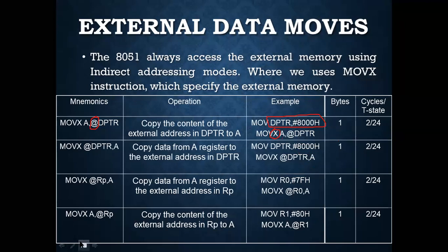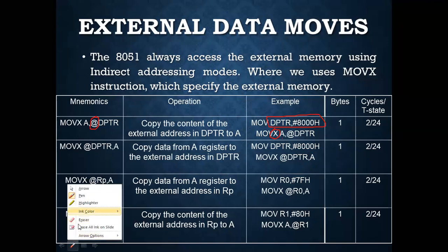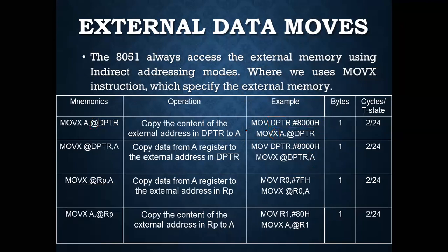Now you may ask, sir, there is written 1 byte. Please don't focus on the initialization instruction; only focus on MOV DPTR and MOVX A, @DPTR. No 8-bit data is there, only mnemonics along with the registers, so it is a single byte instruction. Similarly, this one also.